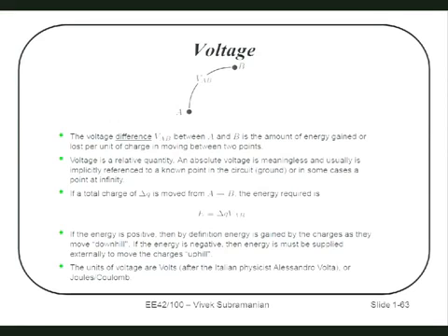But it's not guaranteed to be low resistance. Whereas the ground point, because there's a nice fat wire that's close to a ground point, close to your home, is guaranteed to be low resistance. That's the idea. That's how ground works. So, when I ask you what the voltage difference is, it does not mean the voltage difference between the voltage and ground. The voltage on the lines is the voltage between line and neutral, which should ideally be ground. Yes, question? So where is neutral going?